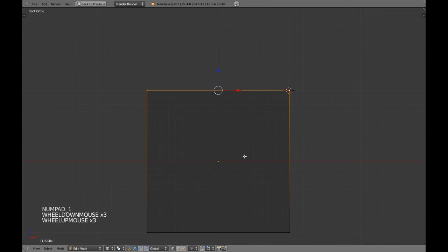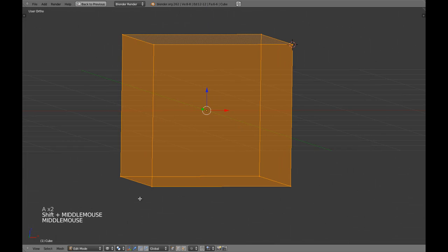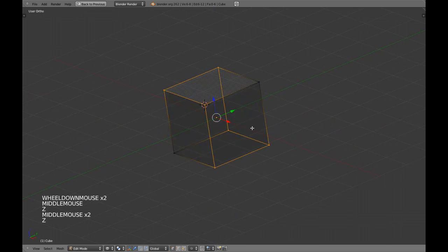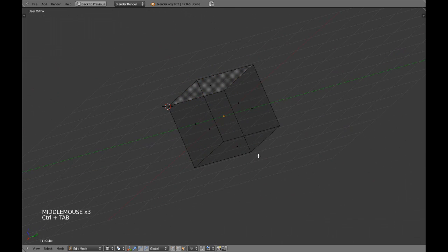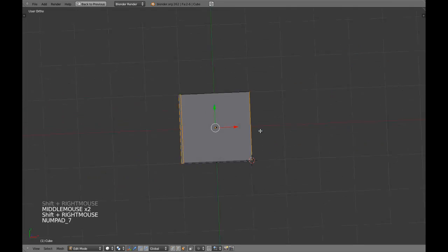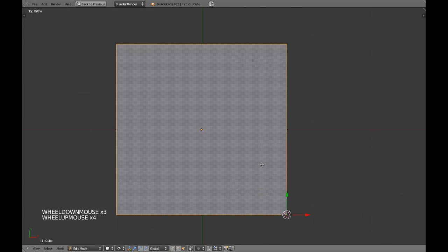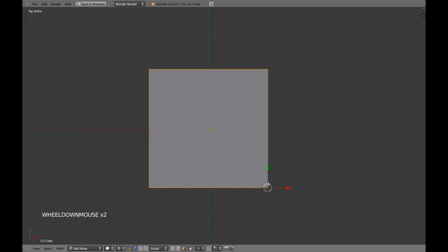For example, if I select the entire object, this will be calculating which is the center of the vertices or faces I'm selecting. Okay, so that's the default with Blender, but you can modify that. I will show you the 3D cursor, and you will notice that the manipulator is now just over the cursor, and it doesn't matter where the object is now; if I change the cursor, the pivot point will change.